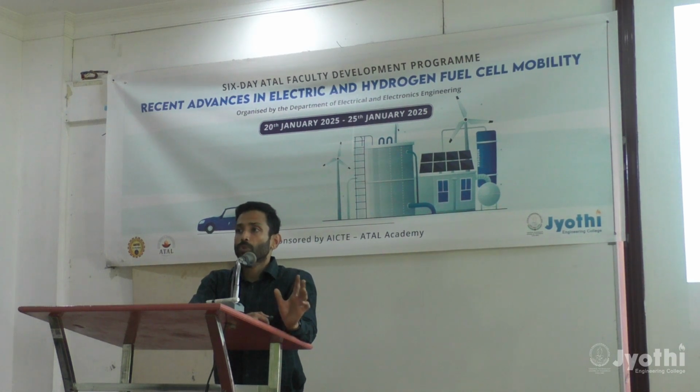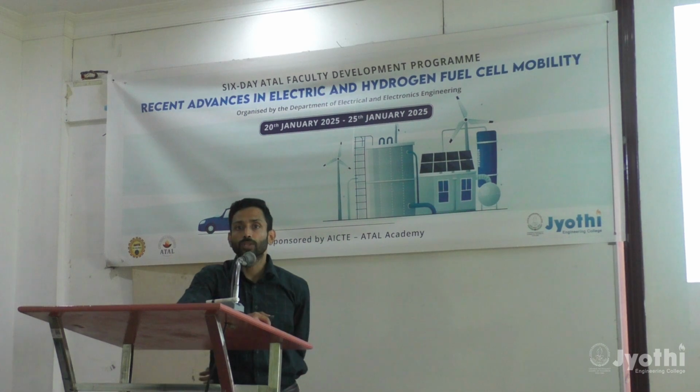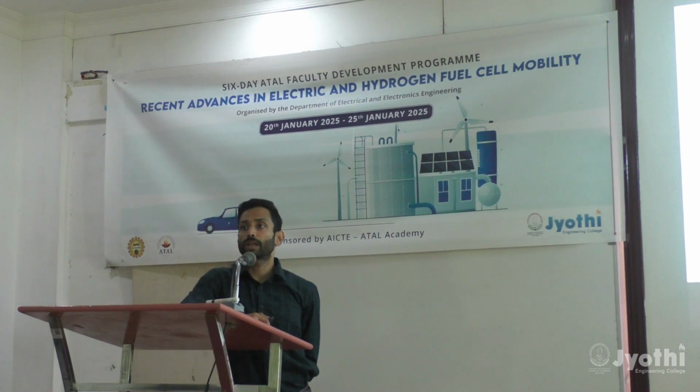So hydrogen production is one challenge, but it is a totally different issue when it comes to storage of hydrogen. Not just because of the very low density, it is also because it can leak quite easily, and it can cause embrittlement of steel, so you cannot store it for very long durations. There can be leakage which can cause explosions. So these are all issues that we will face with hydrogen when you are trying to apply it to mobility applications specifically.